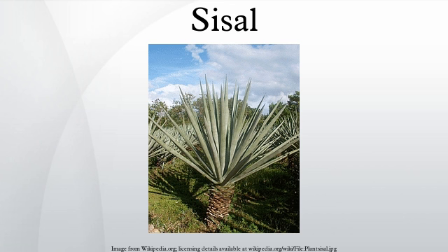Carpets: despite the yarn durability sisal is known for, slight matting of sisal carpeting may occur in high-traffic areas. Sisal carpet does not build up static nor does it trap dust, so vacuuming is the only maintenance required. High-spill areas should be treated with a fiber sealer and for spot removal, a dry cleaning powder is recommended.